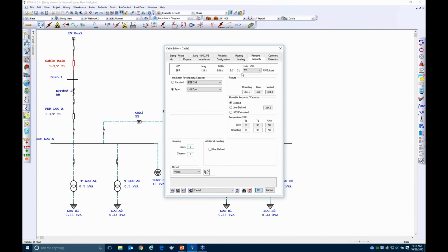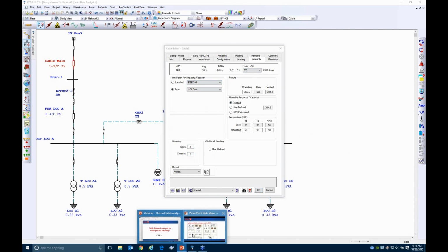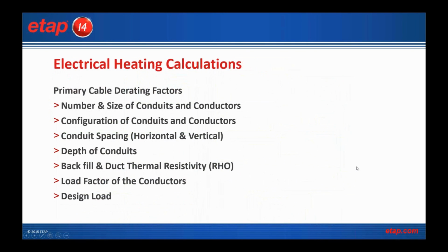What I mean by that is this particular size may be adjacent to other conductors with different sizes, with different voltage levels, and in that case the standards such as NEC or any of the other cable derating standards that we have here, they essentially hit their limitation, and we need to go and do a more detailed thermal analysis, and that's essentially where the underground raceway system steps in.